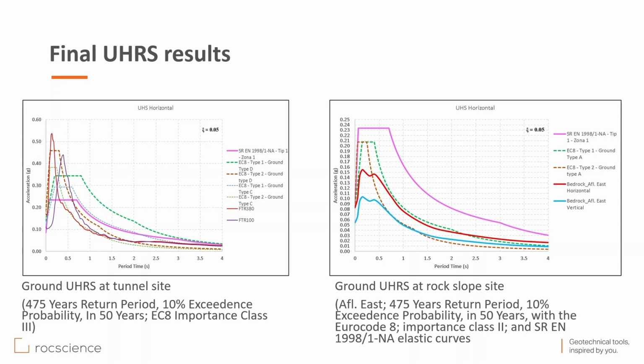time series, there we have a chance to also use the downloaded vertical time series, matched time series, because we always have the measurements in XYZ directions. But in this case, where we don't use real measured time series, there is a possibility to calculate the vertical response spectra from the horizontal one with an empirical equation.